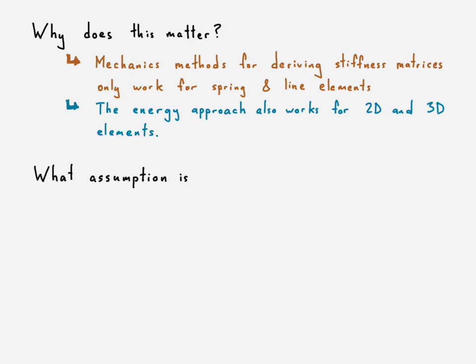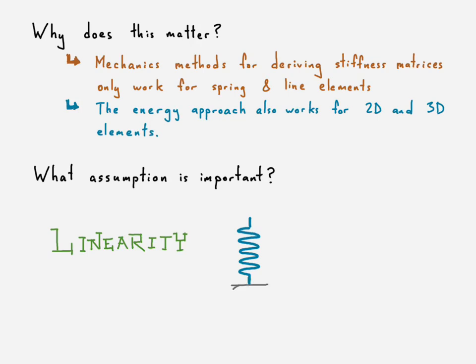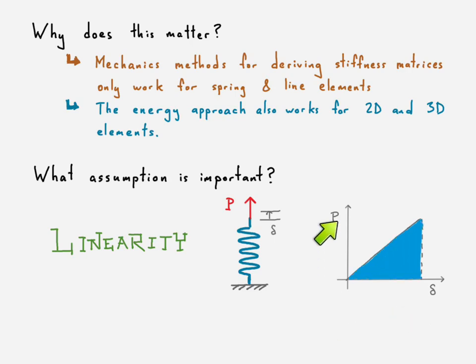The main assumption that is used in this is linearity. If we have this drawing of a spring, and we pull on that spring, we assume that the amount it deforms will increase linearly according to how much force we pull on it. So linearity, that's the big assumption underlying the energy approach that we're going to be using.